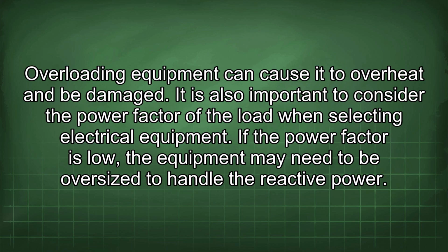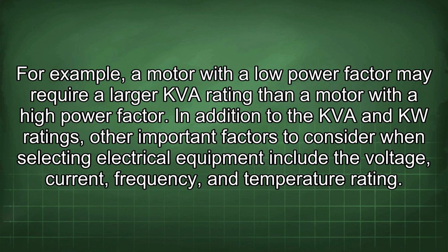Overloading equipment can cause it to overheat and be damaged. It is also important to consider the power factor of the load when selecting electrical equipment. If the power factor is low, the equipment may need to be oversized to handle the reactive power. For example, a motor with a low power factor may require a larger KVA rating than a motor with a